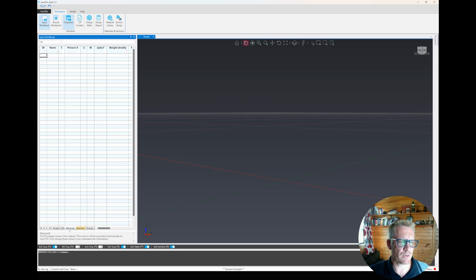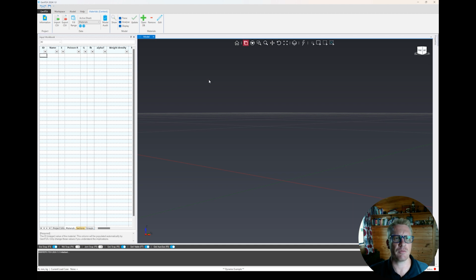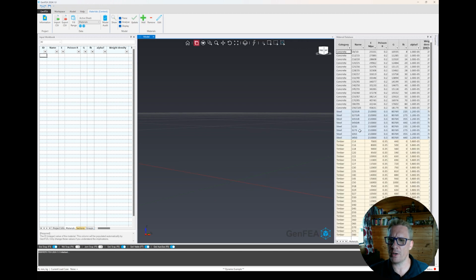The next step was we wanted to head over to the materials input sheet, and you could do this here from the sheet tabs at the bottom or just selecting it here from the drop down at the top. And you activate these dynamic ribbons by selecting the component or the workspace that you're working in. So if I click on any cell on the sheet, the context ribbon for materials in this particular case will appear. If I click on the model, the ribbon changes again, and so on and so forth. So when I've got materials activated, I'm going to click on open, and I'm going to choose the S355 material to add to my project.